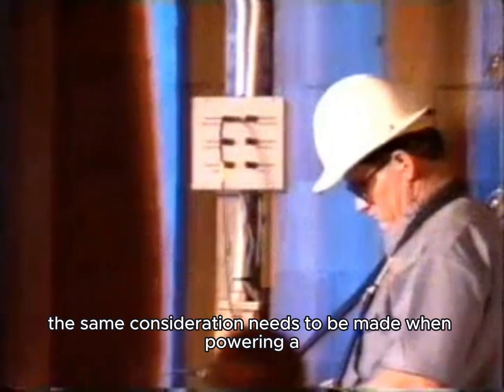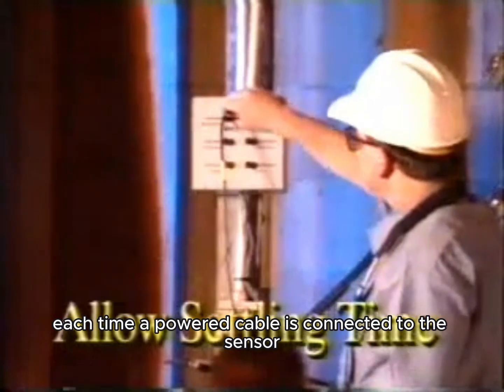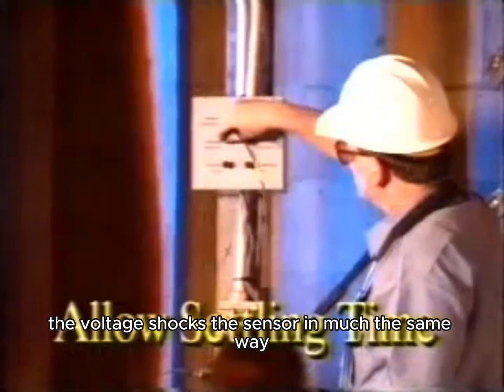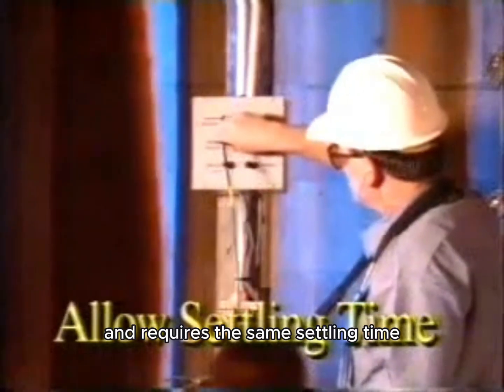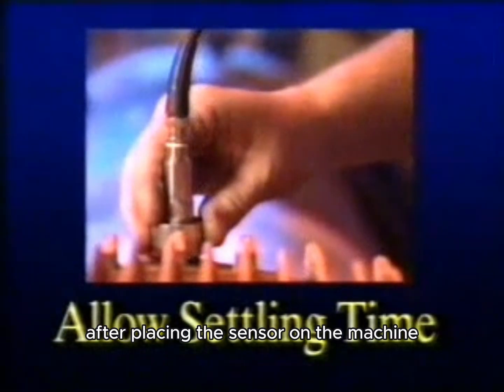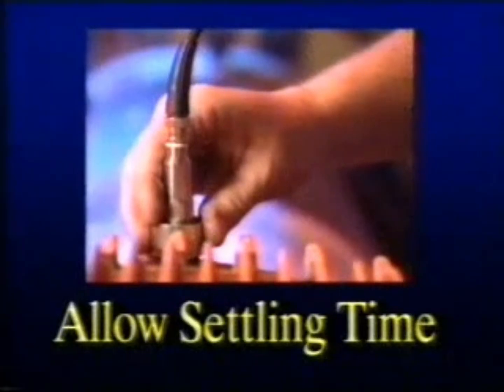The same consideration needs to be made when powering a permanently installed sensor from the panel. Each time a powered cable is connected to the sensor, the voltage shocks the sensor in much the same way and requires the same settling time. Be sure to allow 3 to 5 seconds settling time after placing the sensor on the machine or connecting a powered cable to a permanently installed sensor.